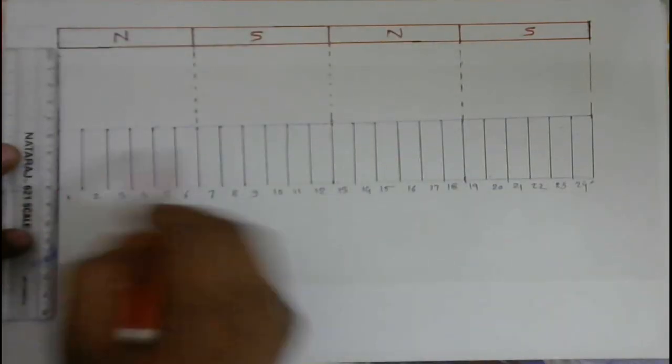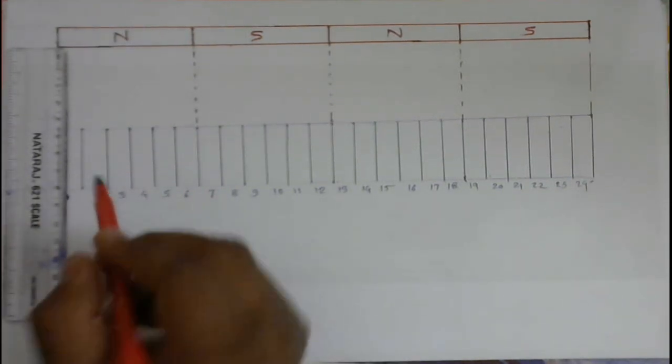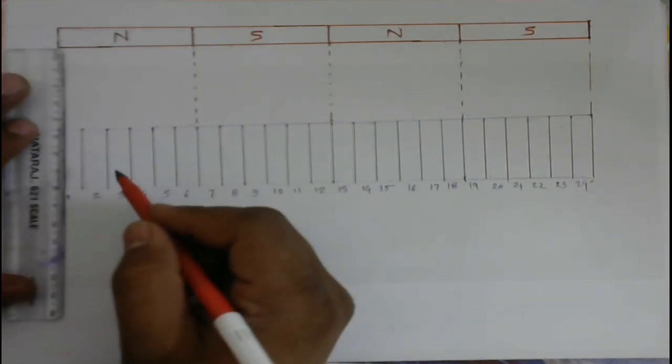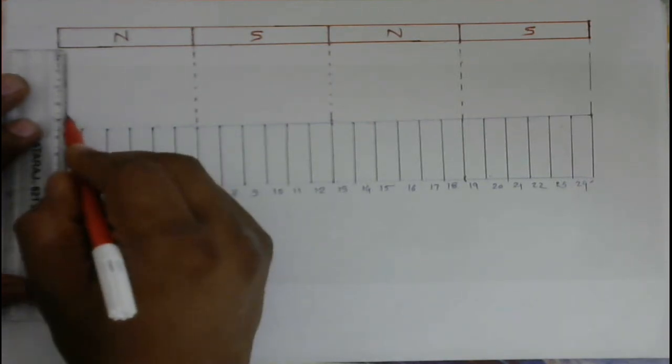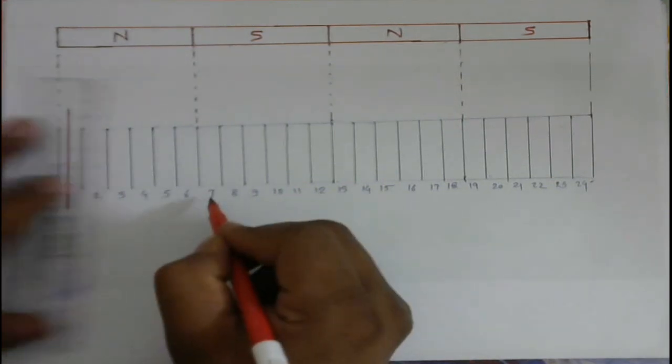As this pole we require to be north, so the current in all the coil sides should be in upward direction. So accordingly we will do the connections and winding. So first I will place the first coil of R phase like this. It will be from 1st to 7th.